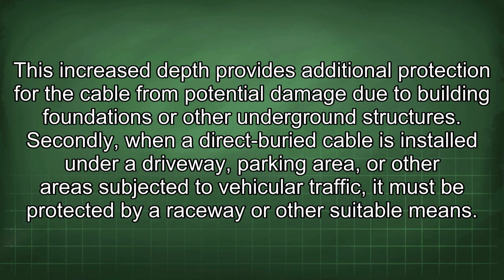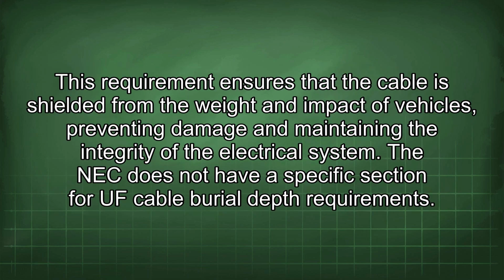Secondly, when a direct buried cable is installed under a driveway, parking area, or other areas subjected to vehicular traffic, it must be protected by a raceway or other suitable means. This requirement ensures that the cable is shielded from the weight and impact of vehicles, preventing damage and maintaining the integrity of the electrical system.